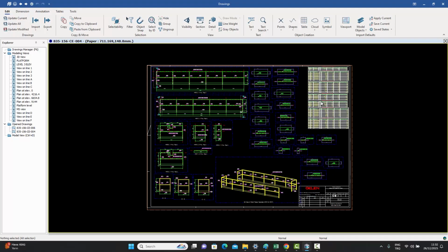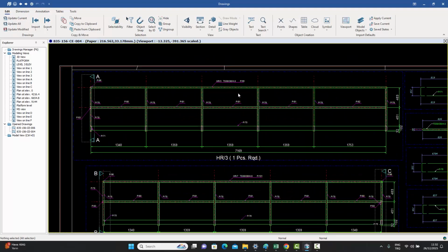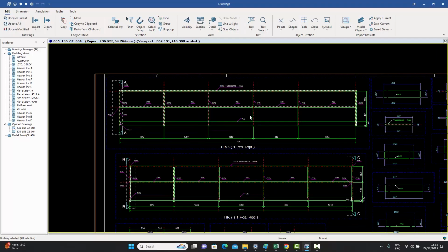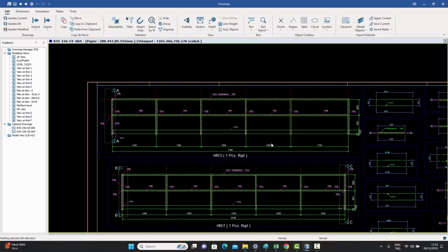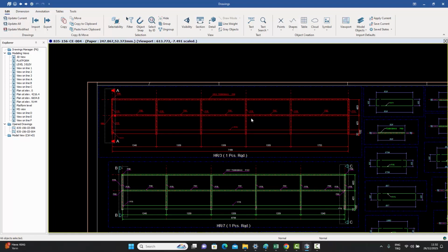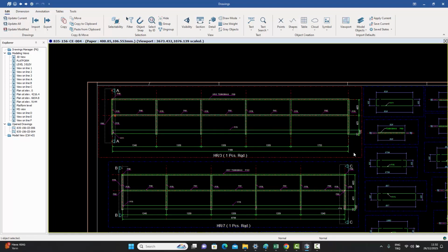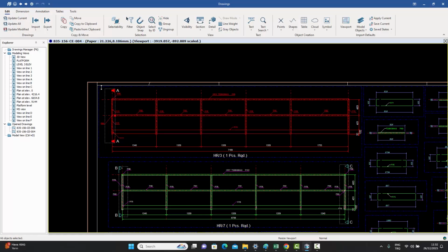That's really useful because instead of carefully selecting individual elements, if I'm zoomed into this viewport and wanted to change the dimensions, I couldn't do a window selection, because I would select all sorts of objects, but I only want the dimensions. So with on-the-fly filtering, you can just do a window selection like that, and press enter,